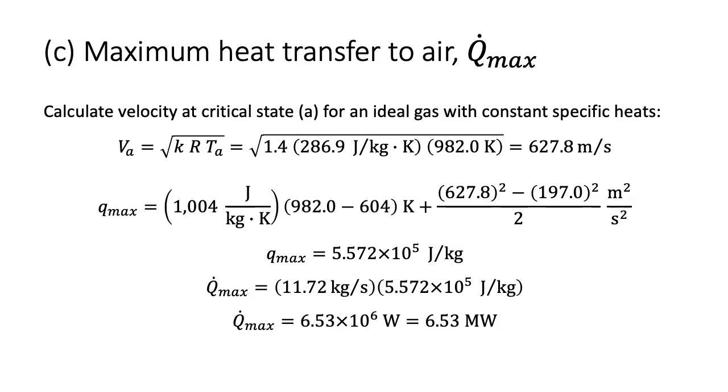Finally, note that adding any more thermal energy to the flow at this point is impossible because the flow is now choked at the critical state, corresponding to a Mach number of 1. Also, the entropy is at its maximum possible value.